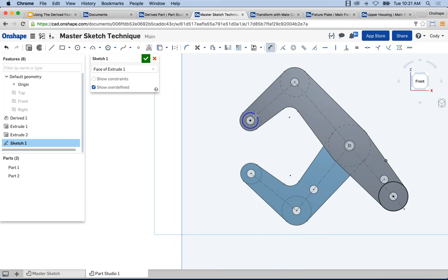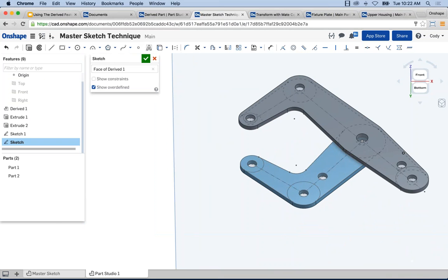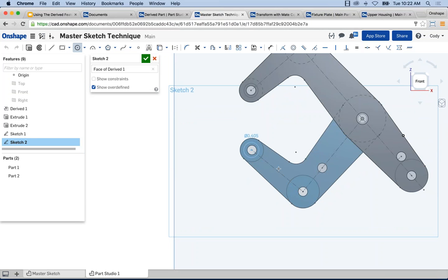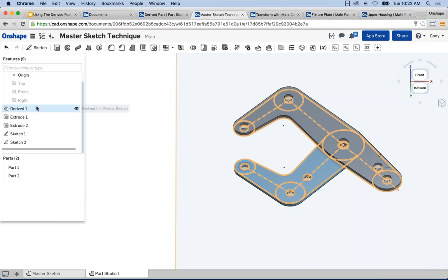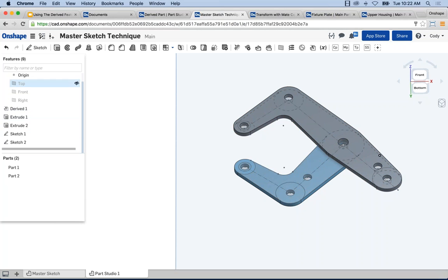So we created two simple circles. We constrained them relative to imported sketches. So now I'm attaching new sketches to imported sketches. Let's do this one more time. Different sketch plane, a few more circles. I'm adding constraints relative to them. So here's a concentric constraint between the previous sketch and this current sketch. We'll set these two to equal. And now I can take these new sketches that are being driven by my inserted sketch and extrude them.